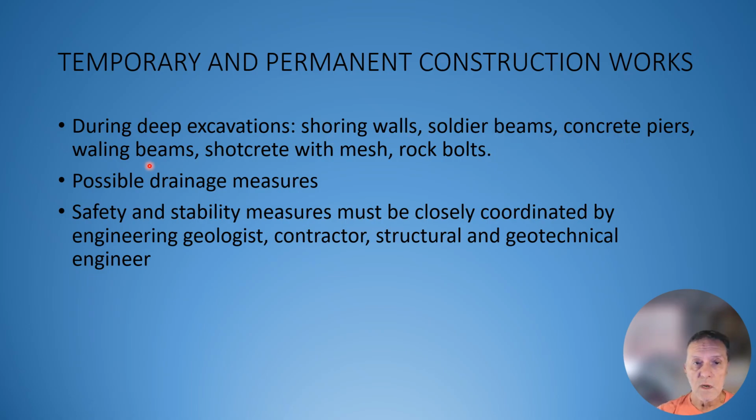You may have concrete piers. All these types of structures to hold back the walls of the excavation while you continue to excavate, especially in unstable rock and soil. When the excavation is proceeding, you have to be aware of drainage measures if you have shallow groundwater that wants to enter the excavation, so you have to provide drainage. You have to have safety and stability measures that are coordinated by everybody on the job.